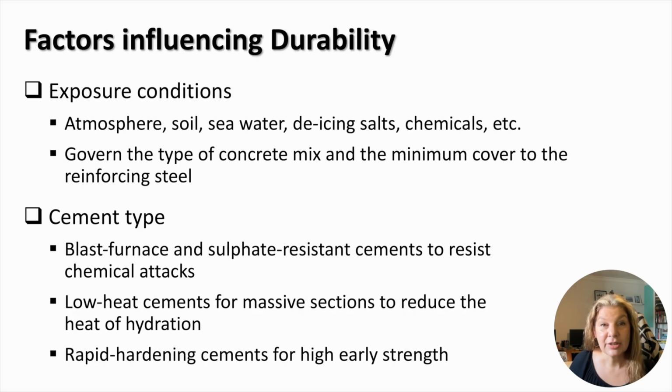The exposure conditions depend on what factors a certain face of a structure is exposed to. It can be atmosphere, soil, seawater, de-icing salts, chemicals, etc. One face of a structure can be exposed to several different factors. For example, part of an offshore structure is submerged, another part is in the splash zone, and the third part is above the splash zone. All these three parts of the structure will be in different exposure situations. The exposure conditions govern the type of concrete mix and the minimum cover to the reinforcing steel.